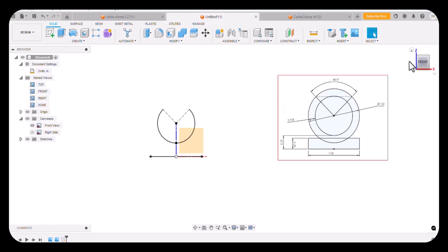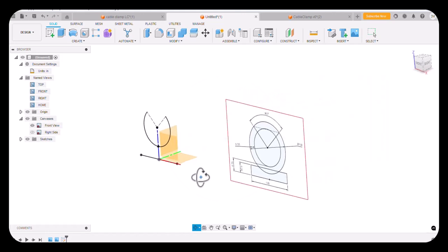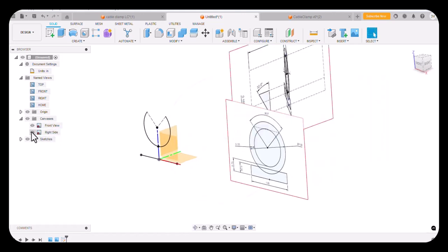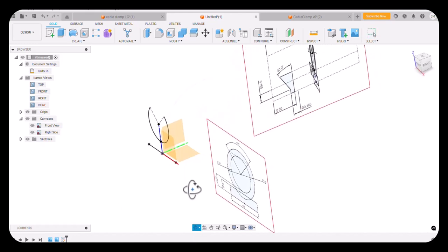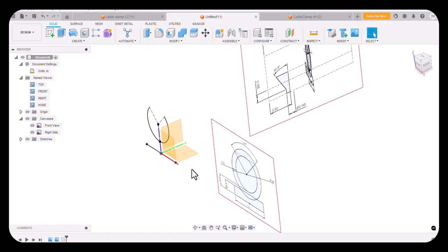I'm then going to finish this sketch, and I'm going to rotate around a little bit, and I want to do a sketch for the countersink that we're going to put in here. And so let me rotate around a little bit more so I can see the dimensions that I want. And I was trying to decide, I could put this countersink sketch right here in this sketch. The results would be exactly the same. Or I could put it over here on this plane. And just to keep things simple, I'm going to do it as two sketches, but it could be done as one sketch added to this sketch. Or it could be put on this plane as well.